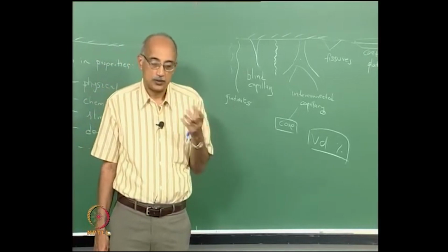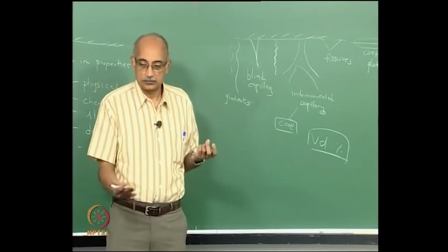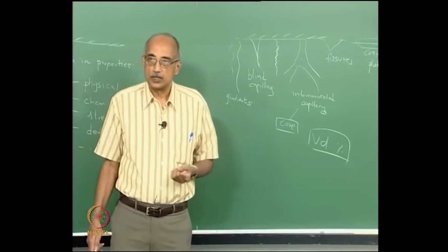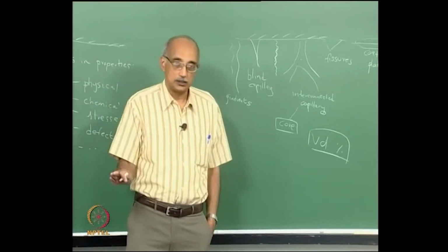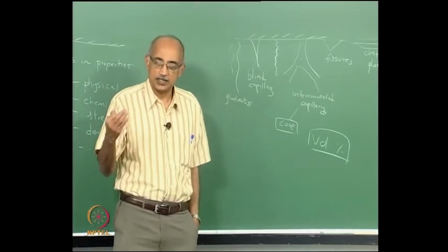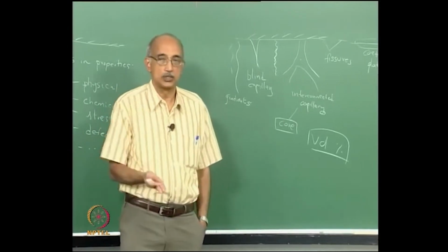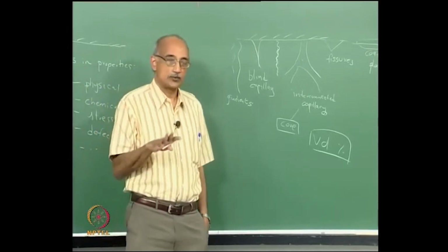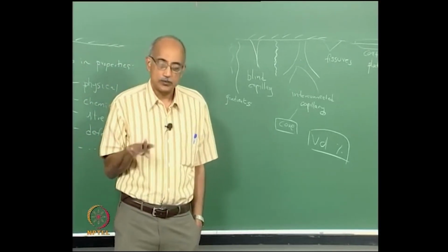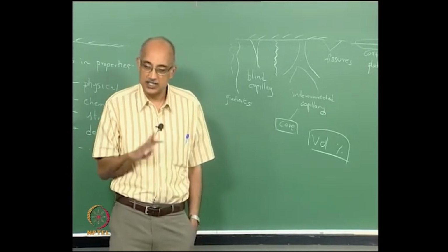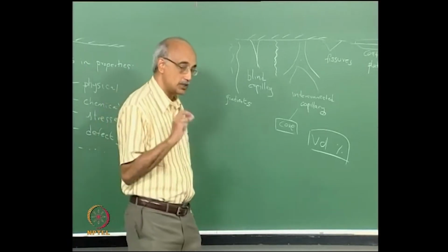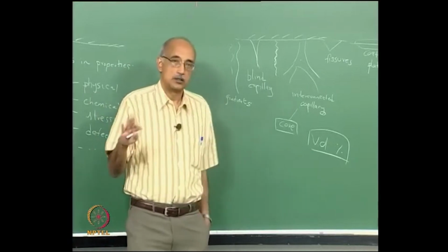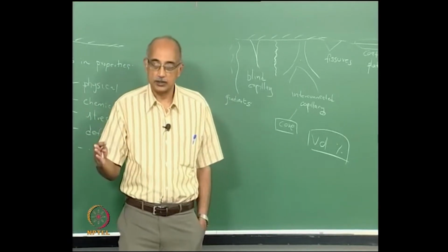So if you have, for example, a steel table that has nickel plating on it, then the surface is not steel, it's nickel because that is the surface that is exposed to the surrounding fluid. So we have to be very clear in our definition that what we call the surface is not based upon the material that it's made of, but rather the physical surface that comes in contact with the environment.